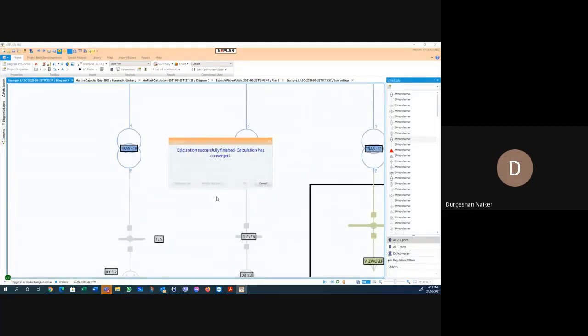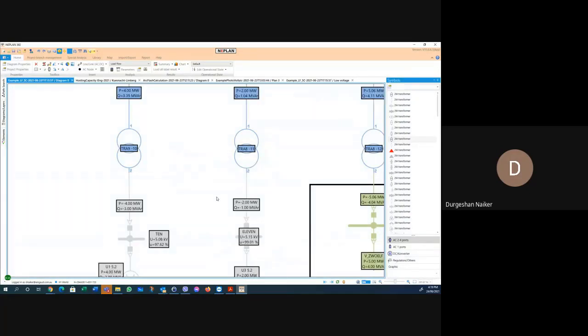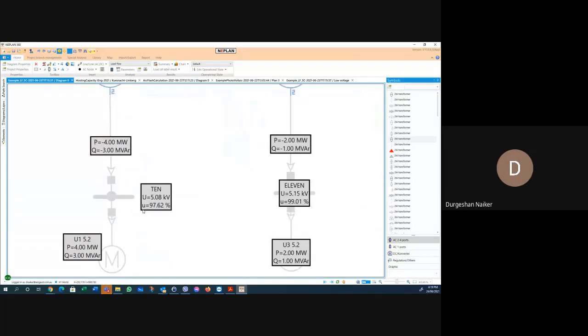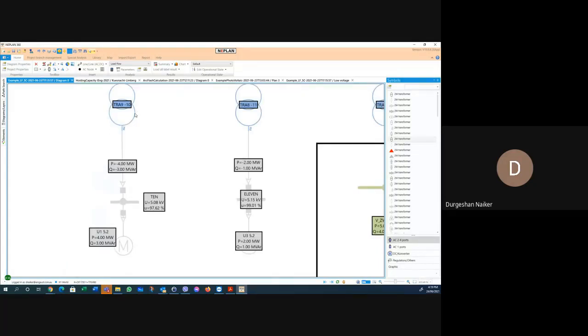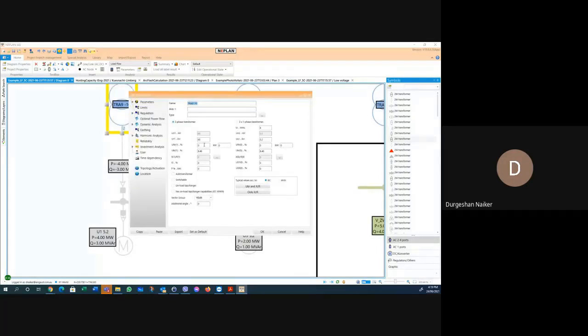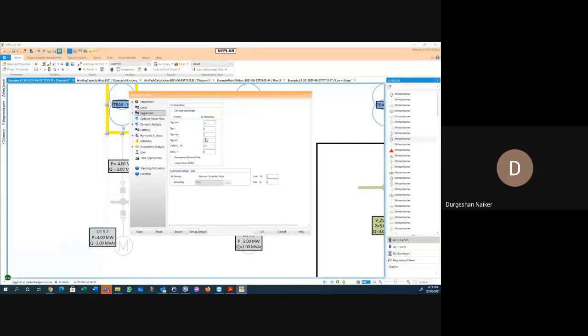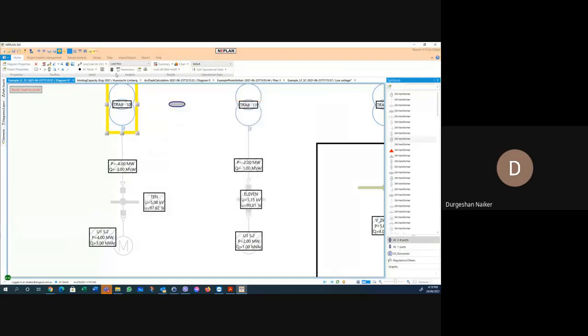So as an engineer, you can tell the people out there that when you're doing this one, make sure you put your tap at 1 for this transformer so that you don't get a voltage drop issue here. So you can see you have simulated it, and you found that you are getting 97 here. Okay. And that is good enough for you, probably. If you go to tap, next step, it might be even more. It will increase to probably 100% because we are putting too much now. And that is also fine. You know, it's getting the full voltage.